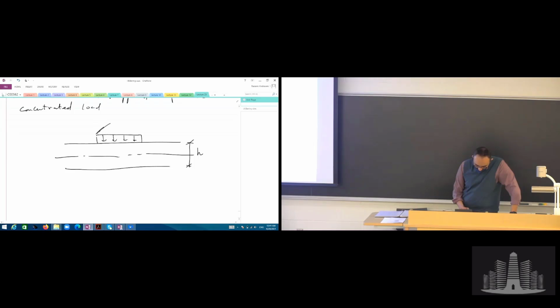And in the other, this is the transverse direction, obviously. In the longitudinal direction here, it goes like this. So the resultant of the pressure is going to be how much, guys? What's the wheel load there? 16. Very good. 16 kips. So that's going to be a pressure resulting in a full load of 16 kips, the wheel load.